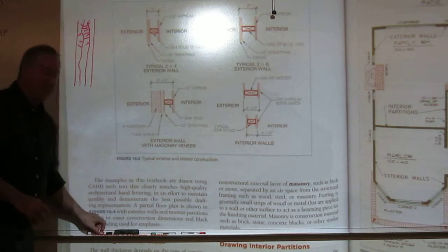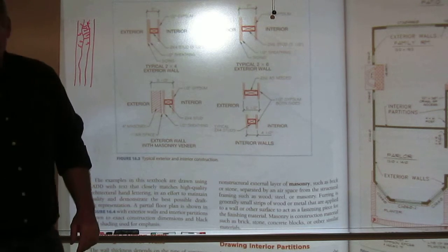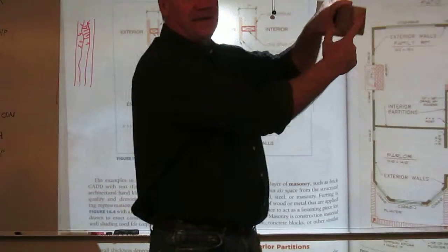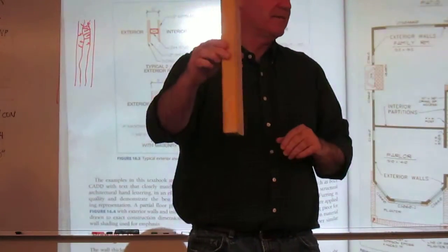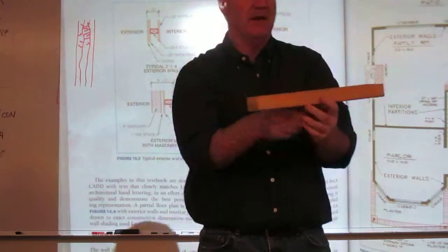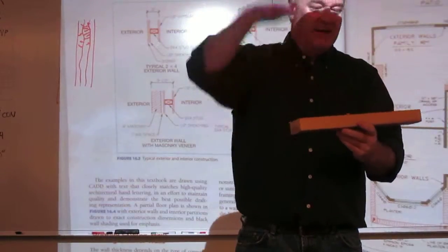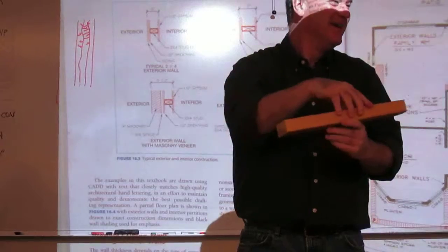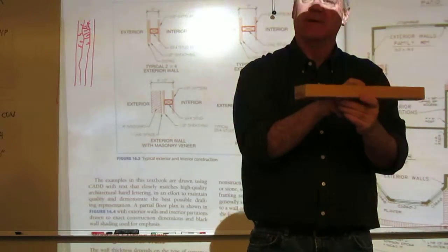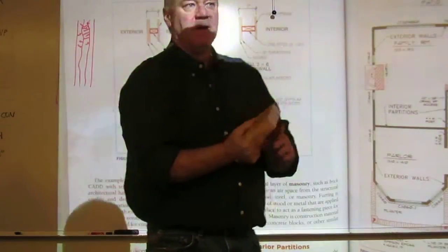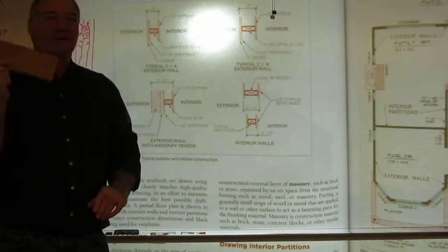So that's one of the reasons we take wood and we cut it. You'll look at every one of these, you're going to see the end grain at the end of them because we're cutting parallel with that grain. That keeps the strength. If we cut them this way, we'd have to have a huge tree to get an 8-footer, but you would be cutting across that grain and its strength would be greatly reduced. Really pretty amazing material.